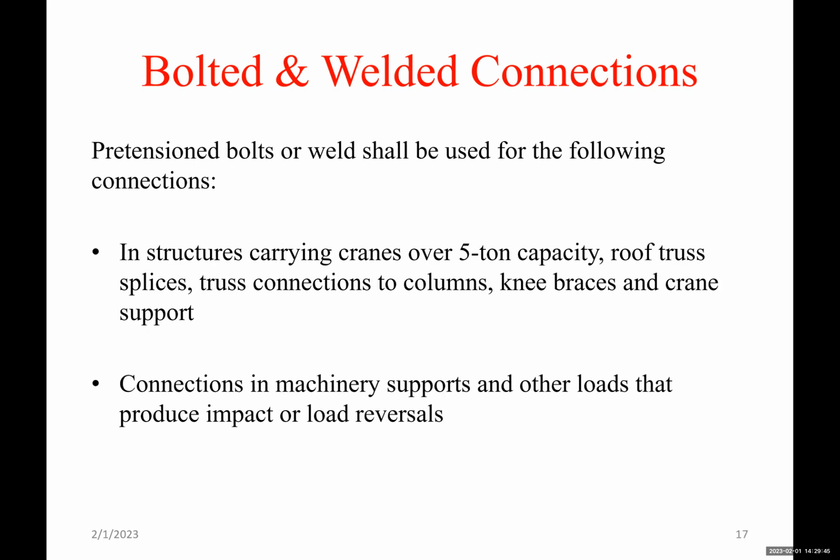In structures carrying cranes over 5-ton capacity, roof truss splices, truss connections to columns, knee braces, and crane supports. In those, use pre-tension bolts or weld, of course, because that will prevent any slip.